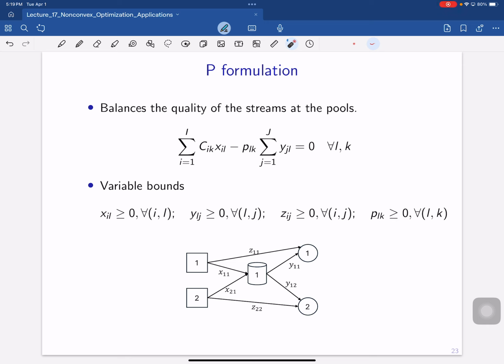Right. So essentially, you have some mass balance constraints, both on the flows and on different quantities, right? Because physically what you need to do is to enforce some quality specifications like sulfur concentration at the product. But in order to do that, you need some equations to calculate the sulfur concentration, right? Not only do you need to have the total mass balance, but you have the mass balance for each quantity, like the mass balance on the green and red, respectively.